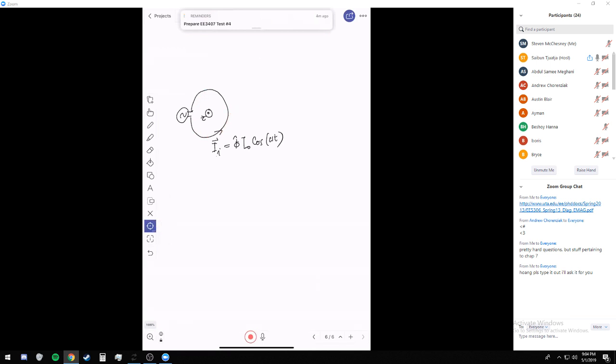The current is flowing like this. So what happened to the field? The field follows the right-hand rule. So I have a field that is going out from the inside, correct? And then going in on the outside of the loop, right? So everywhere outside the loop, the field is like this. Does that make sense? And this field, of course, also produces an electric field. So I have both E and H outside here, right?